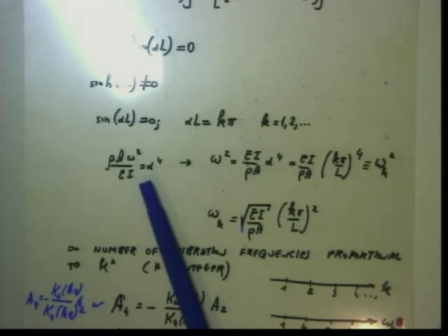Yes. So is omega k a magnitude? No, omega k is not a magnitude. Omega k is a natural frequency. It is the value of the k-th frequency. The magnitude has to do with the response. We do not deal with the response yet. We deal with natural frequency. What is natural frequency? Natural frequency does not depend upon excitation. It is natural. It only depends upon the beam's characteristics. It depends on modulus of